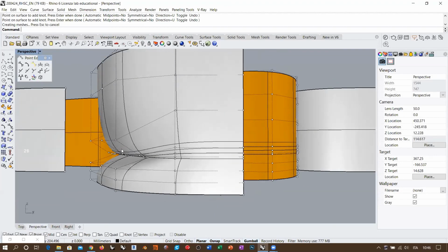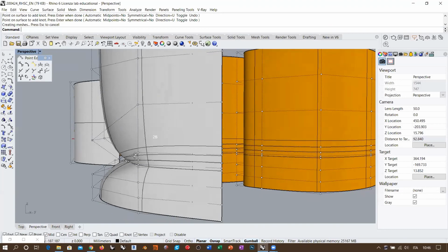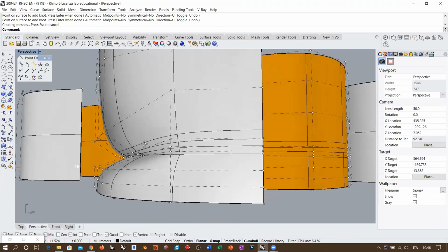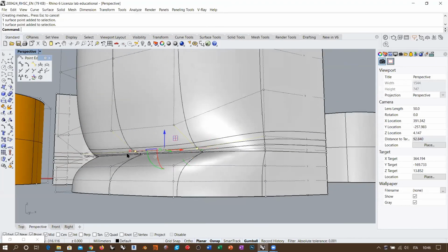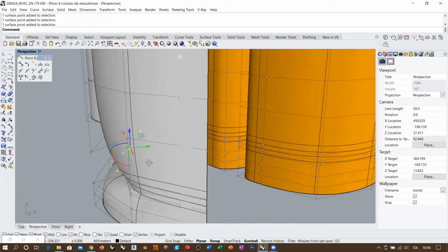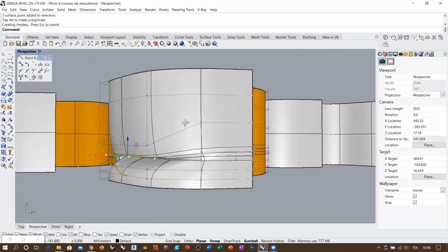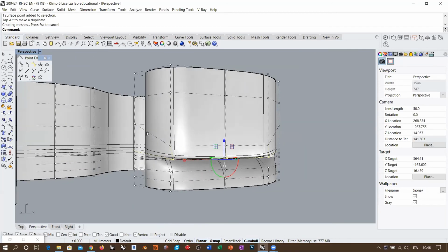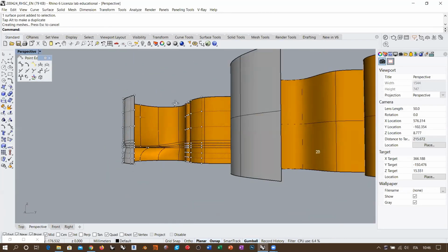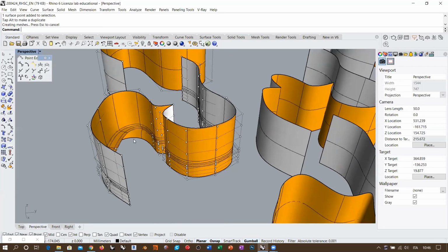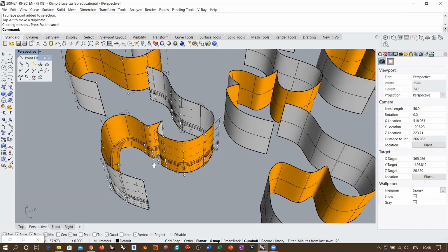So I have more control points in this area, and this is naturally starting to pull the curve down. And if I, for example, take these control points in this area, like these 3 here, and move them toward the outside, now I am creating the flat part without disturbing the rest of our surface. Okay, so everything here is being conducted directly with direct topological editing.